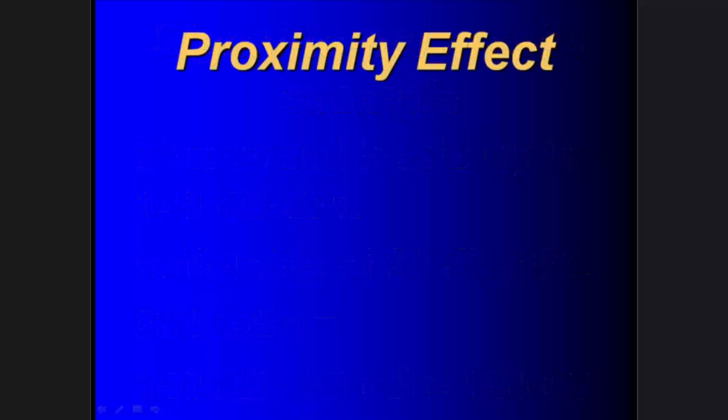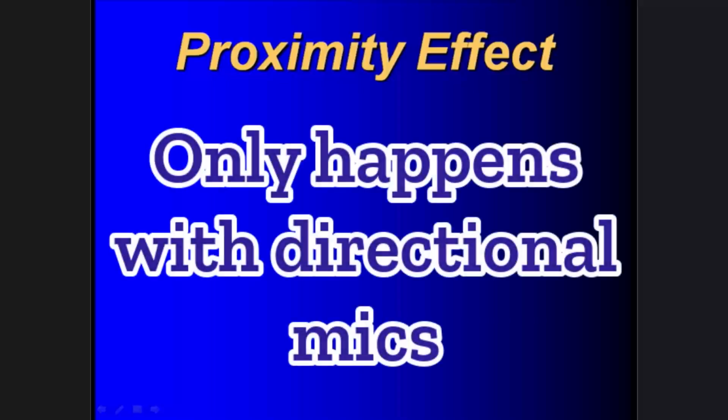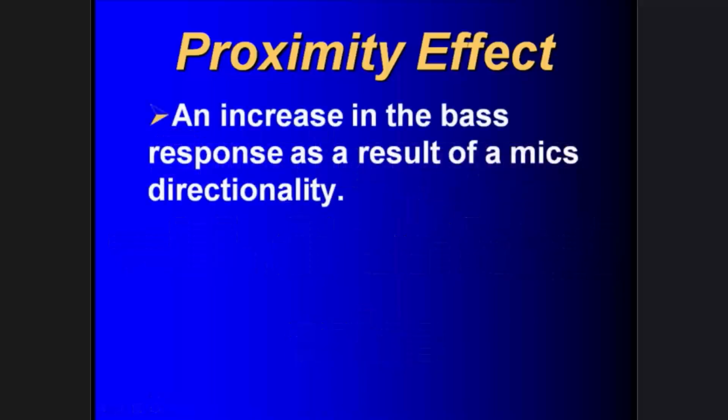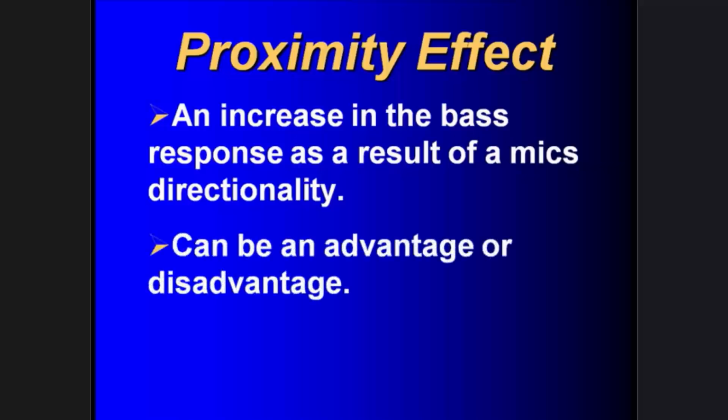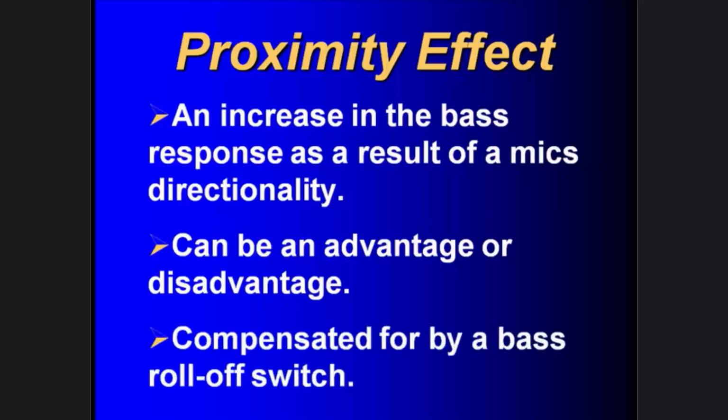The sixth electrical characteristic might be considered the proximity effect, but this only happens with directional microphones. It's the increase in the bass response as a result of this mic's directionality. The closer you get to the microphone, the more the bass increases. And this can be an advantage or it can be a disadvantage, so they put a switch in the microphone to roll off those bass frequencies.